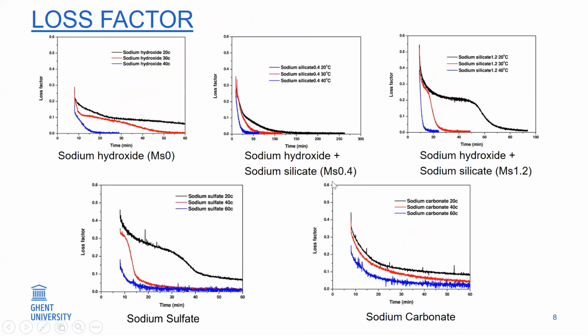The most important thing we want to discuss is the loss factor. Indeed, in the AAC paste suspension, there exist different forces. The most important are the interparticle interaction force and the Brownian forces. Due to the increased temperature of the curing condition, the movement of the particles was accelerated and the interparticle interaction was also enhanced. And at rest, on one side, the colloidal interactions due to the van der Waals attractive force lead to the formation of flocculated structures.